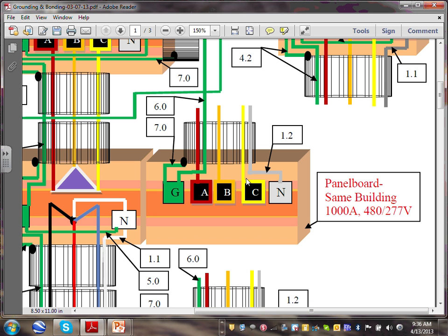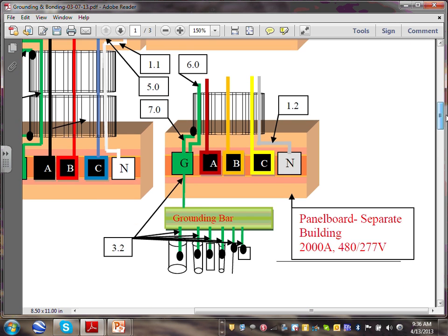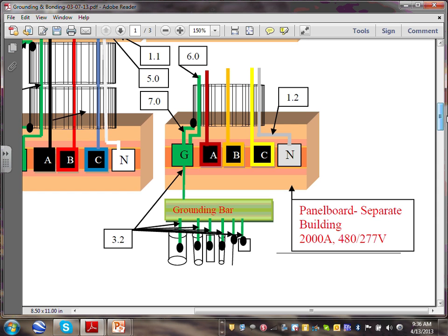Before I go, I'm going to go to another sub panel in a different building now. And the reason why a different building is because there's a grounding and bonding requirement. So let's go a little bit down, guys, right in here. I'm going to focus on another switchgear or panel board in a separate building. So I took another 2000 amp out of this switchgear to a separate building, physically separated from each other, or structure, and I have another panel there, and I need to feed it.